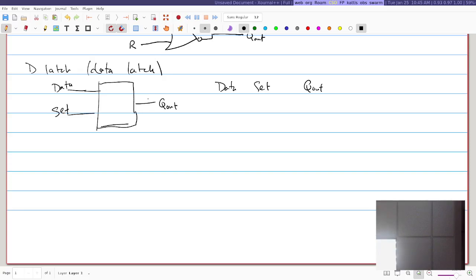Different signals are going to take different amounts of time to get through the circuit. You can imagine weird things happen if you say, okay, set it now, but at that time this signal did make it, but this signal hasn't made it yet, and you're getting weird inconsistent things. So we need some way to synchronize things, so that even though different signals take different amounts of time, we have some point where everything should be okay now. Now we're all going to save the memory at the same time, because this is when we know for sure that everything's arrived, so now we can safely read and move on to the next thing.